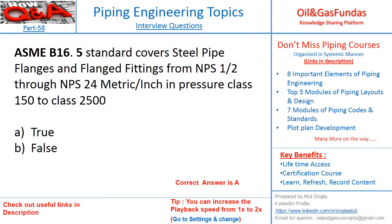This statement is true. This is telling us what is covered, what sizes and ratings are covered under the B16.5 standard. So this standard is covering all the conditions related to steel pipes, flanges and flanged fittings also. Half inch to 24 inch size and 150 to 2500 class rating. So this is something which we need to remember, what is basically covered in B16.5.